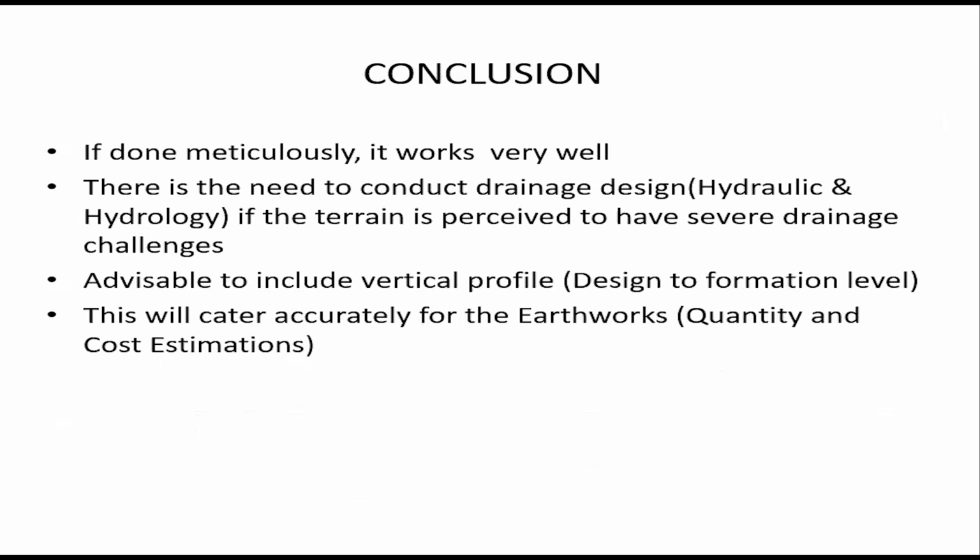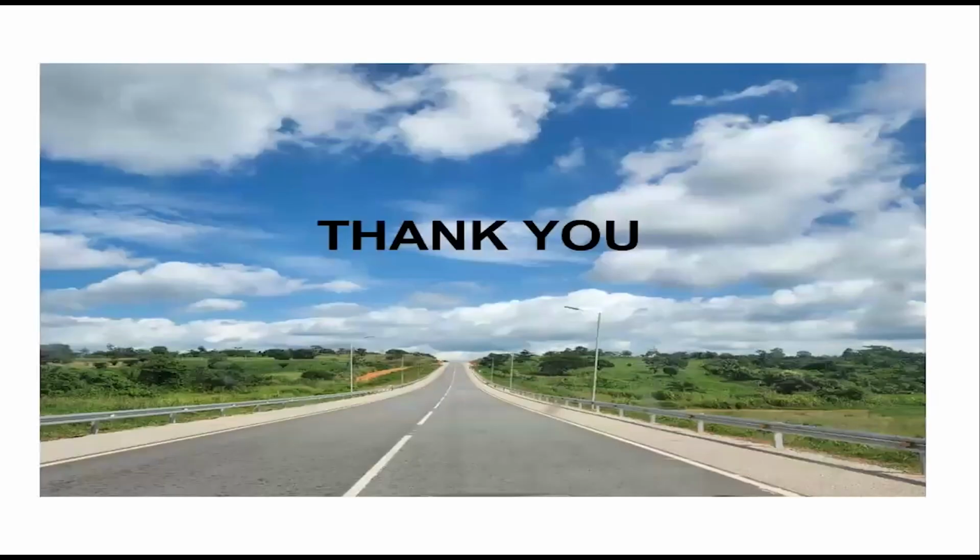In conclusion, a line diagram, if done meticulously, works very well. Then there is a need to conduct drainage design, that is hydraulics and hydrology. If the terrain is perceived to have severe drainage challenges, then you have to do a proper drainage design. Then it's advisable to include a vertical profile designed to formation, as I just said. And this will cater accurately for the earthworks, that is quantity and cost estimation. So thank you very much.